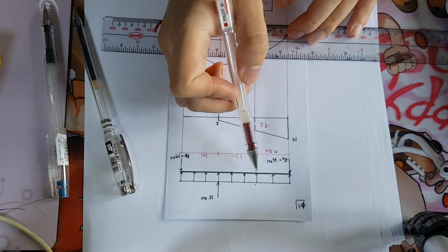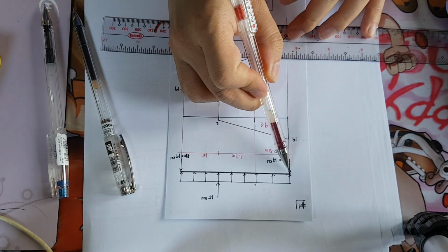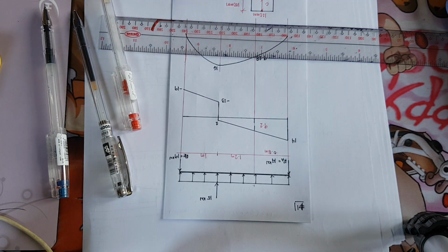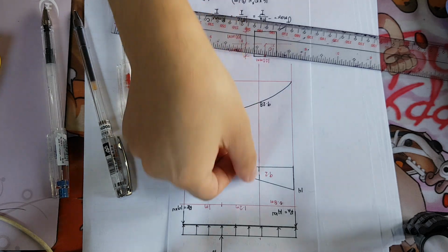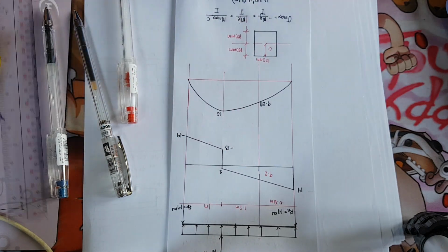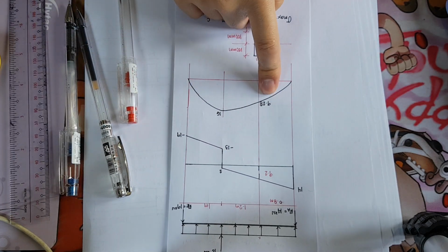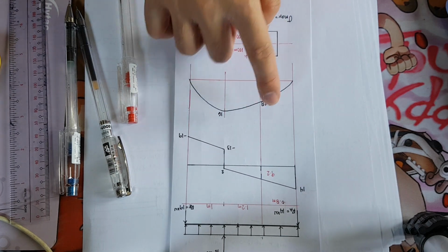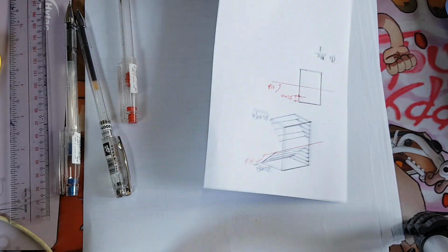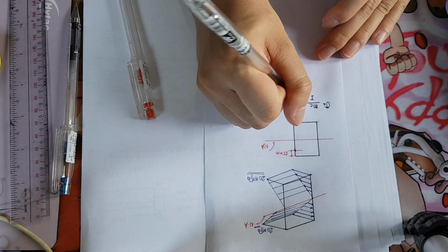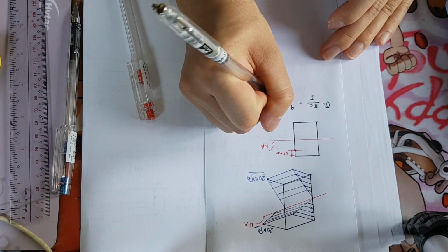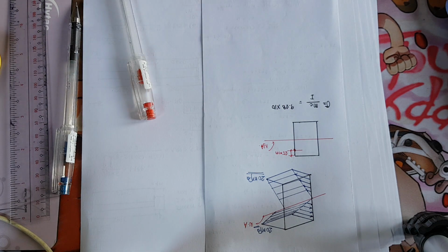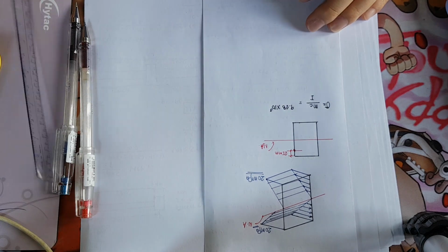The shear 0.8 meters from a support is 9.2 kilonewtons. And the moment at that point is 9.28 kilonewton-meters. So we can solve the area here and we can get the moment here. And the moment is 9.28. So substituting that to our equation, we have 9.28 times 10 raised to 3 times c.